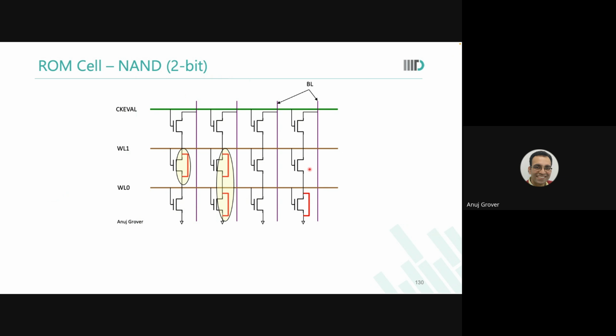Unlike a transition from 6T to 8T or a smaller high density 6T to a high current 6T, things are very different now. It's something like when you make the pass gates PMOS instead of NMOS, we said oh, now the bit line will be pre-charged to 0 and word line will be active low and so many things we talked about when we were talking about the 6T memory cell. Are you with me? So similarly, when you transition from NAND to NOR or vice versa, the way you handle your word lines changes. Your state machine changes. The control logic changes. Is that okay?